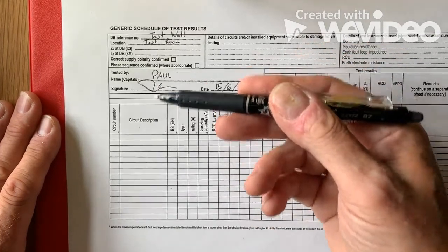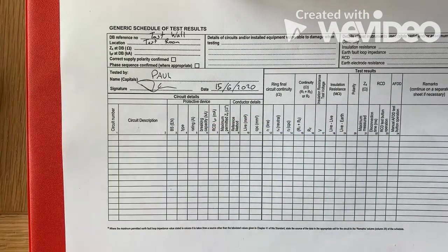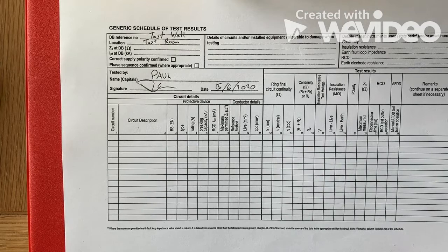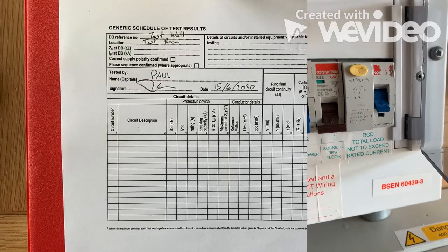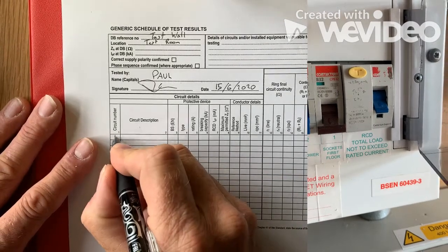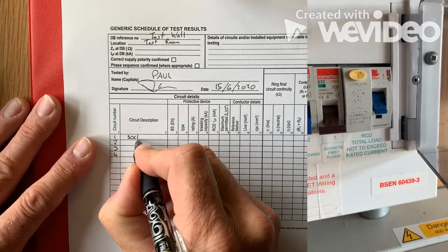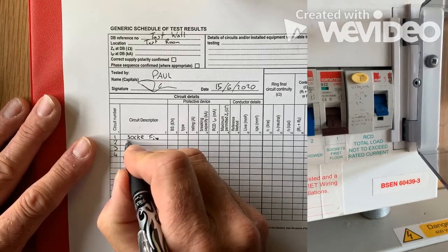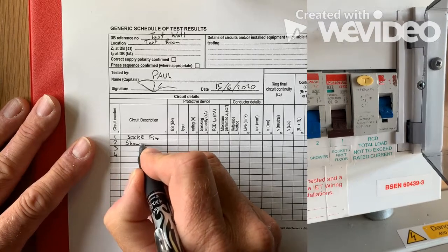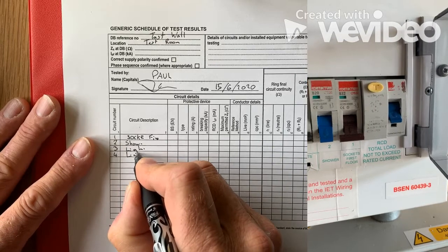And the next thing is that we're going to fill out this board. So we're going to do this bit by bit as we go, going through all the different circuits that we've got, starting from here. So we've got circuits, first floor, shower, and then we've got lights and lights. So we've got sockets, so we've got 1, 2, 3, and 4. So we've got sockets first, then we've got shower. I'll fill these out a bit neater afterwards. Shower, and then we've got lights and lights.